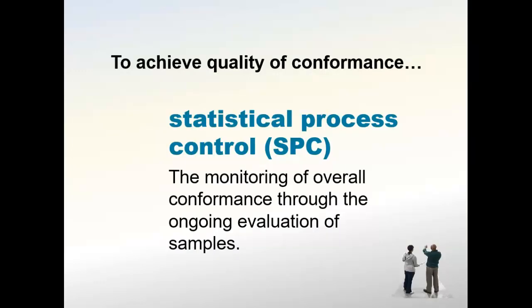Now, much of quality control is formally known as statistical process control, or SPC. It's a set of concepts, tools, and procedures that monitor active processes by sampling output. So if this sampling suggests that only natural variation is present in the output, the process is said to be in control. However, if the sampling indicates that assignable variation is present, the process is then declared out of control, and the decision to stop production and search for its root cause usually follows.